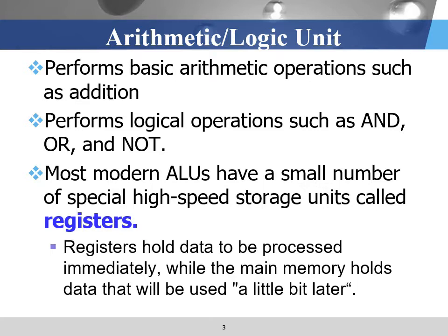The ALU will perform basic arithmetic operations such as addition, and logical operations such as AND, OR, and NOT. Most modern ALUs have a small number of special high-speed storage units called registers. The registers will hold data to be processed immediately, while the main memory will hold the data that will be used a little bit later.